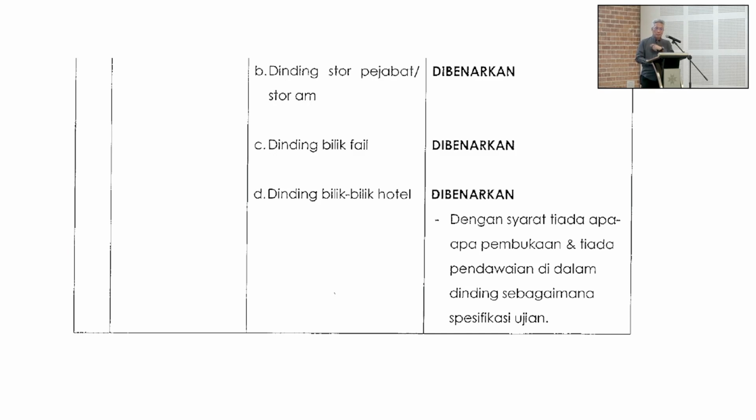Dinding store pejabat, dinding bilik file. These are all the little storages within your own office. Bomba always say, even if you define the space under a stair as a store, this one must be fire rated. We say, you must be kidding, I'm only going to put my broom inside under the stair. They say no, must have fire rating. So now we don't even classify the area, isn't it? We don't say store di bawah tangga anymore. We just leave it open. Tell the developer, save yourself the wall, save yourself the door. Don't even call it a store. If the owner wants to build it, they can spend their own money to do it.